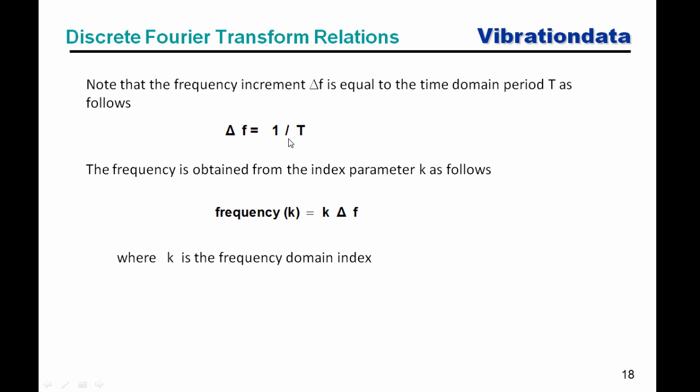And one of the points of this, if we need finer resolution, we should take a longer and longer time duration. So in that sense, the longer the time duration we measure, the better off we are. But of course, there's some practical limitations to that. If we're measuring a pyrotechnic shock event, and it only lasts a matter of milliseconds, then we're going to measure for a couple of milliseconds. We might allow some quiet period thereafter, but we're not going to take a pyrotechnic shock that lasts milliseconds and measure it for 10 hours. It just doesn't make sense. But if we have more of a steady state type stationary vibration, then it is very advantageous to take a longer duration in the time domain measurement.